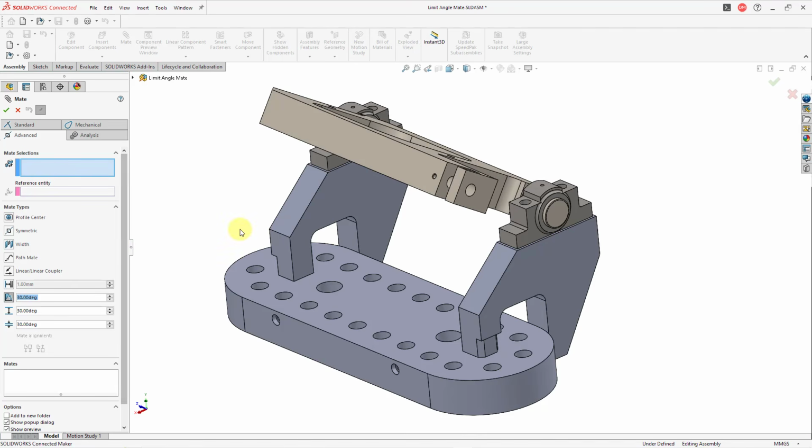In Creo Parametric, I can select surfaces that don't go through the axis of rotation, and it'll end up creating an internal plane going through the axis of rotation in order to use as one of the references for the angle. I just found that that does not work so well in SolidWorks.